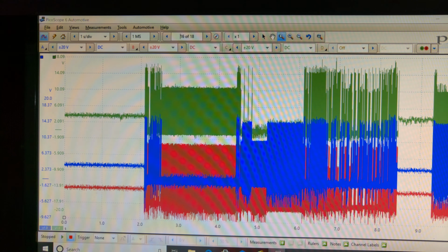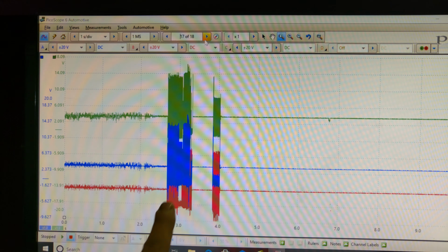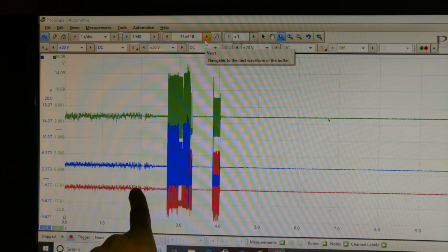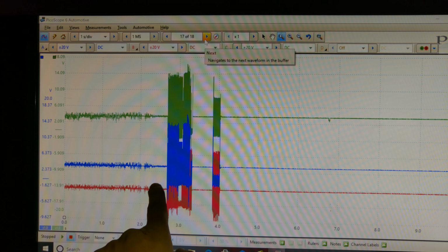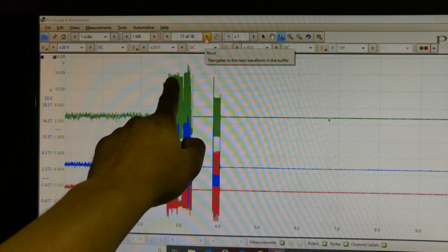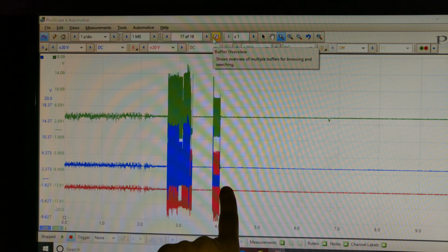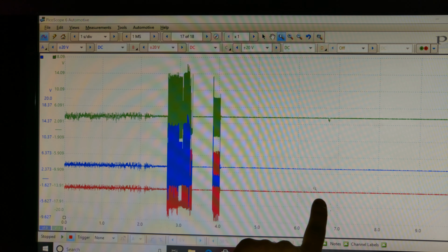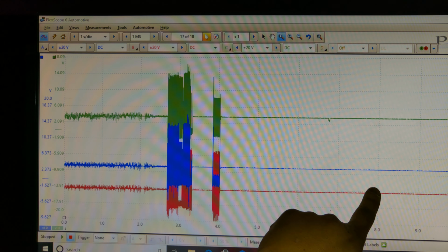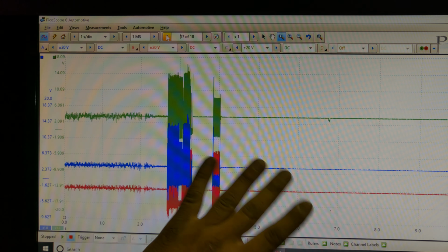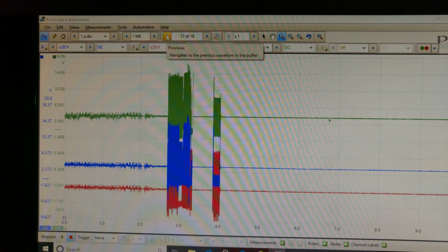some activity. And as soon as I went back to park, it went down to 4 volts again, the bias voltage, and I went back to reverse again, and it did the same thing, and I turned the car off, and it stays at 4 volts for an extended period of time, like I said, until the TCM is switched off on its own.